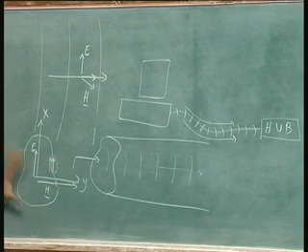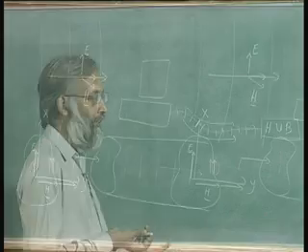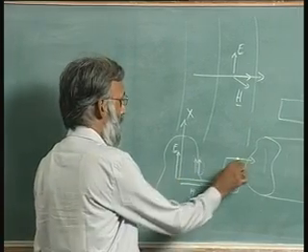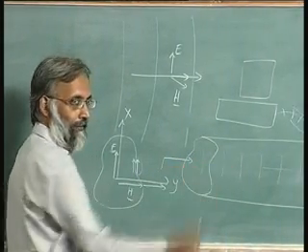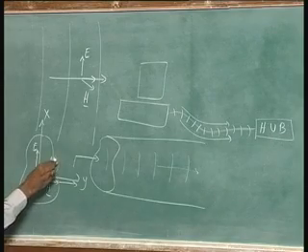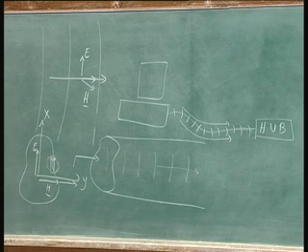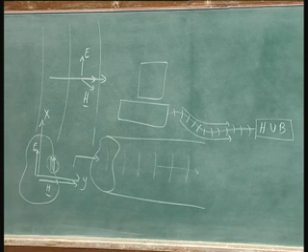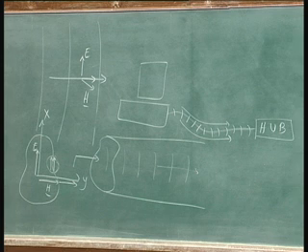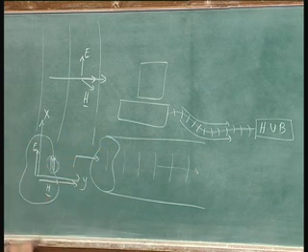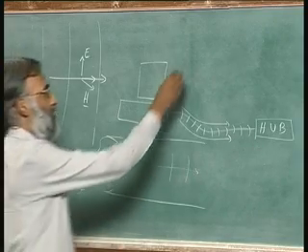If a plane wave is to survive, it must change. It must be a different kind of wave. It must actually vary not only in z, but it must also vary in x and in y. And how must it vary? It must vary by becoming 0 wherever the electric field tries to be tangential, and the magnetic field must become 0 wherever it is trying to be normal. There are such solutions, and the study of waves flowing through pipes, it's a very important subject. It's called waveguide theory.